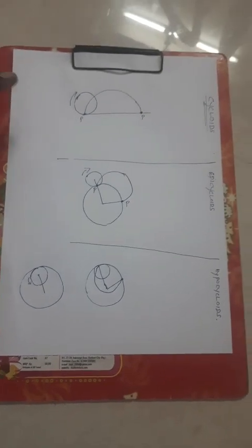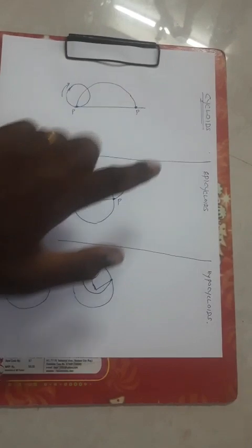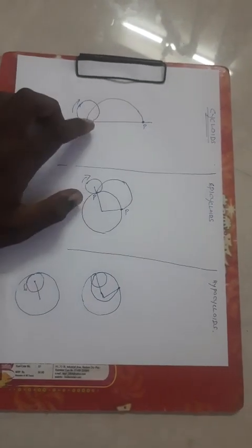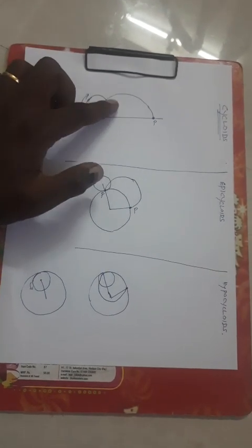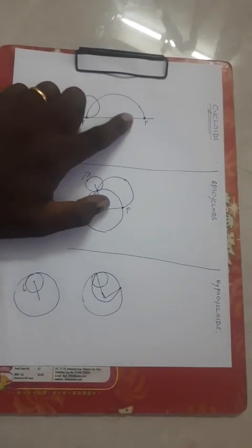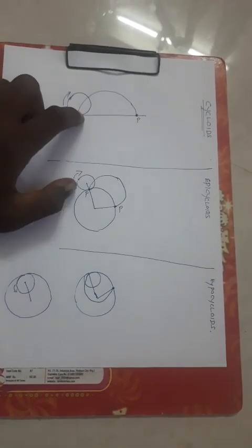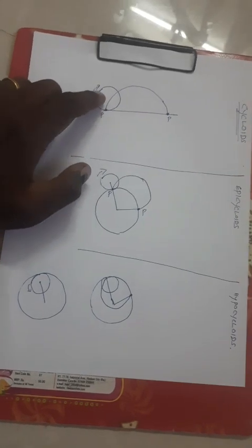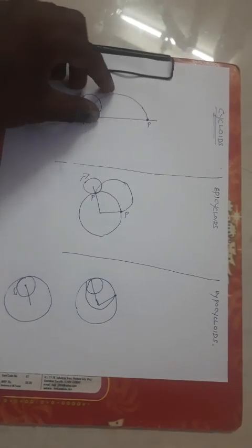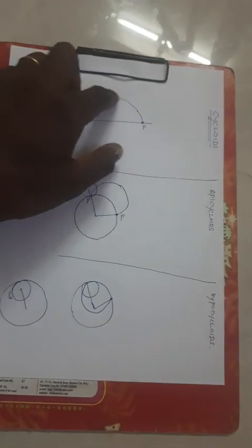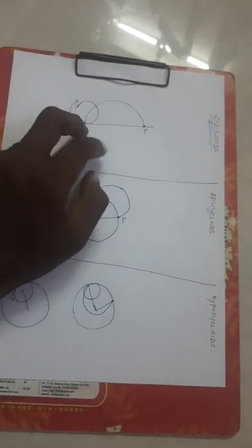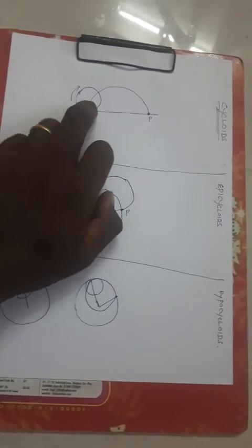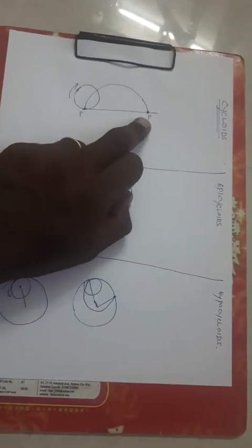Now listen, this is about cycloid, epicycloid and hypocycloid. If I have a circle, the circle rolls horizontally without any slipping. If I have a point P here, the circle will roll like this, and again this point P touches the ground after some distance. The distance will be the circumference of the circle, and this will be considered as one complete revolution.